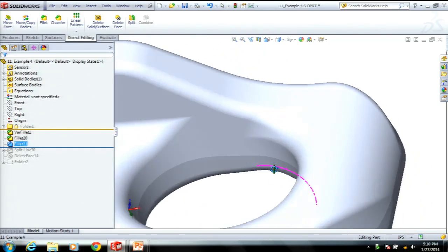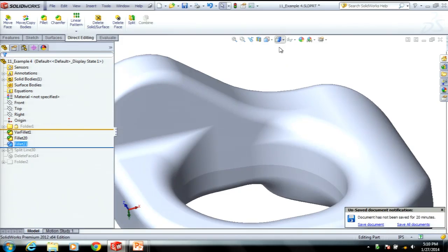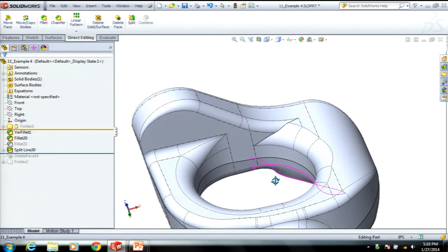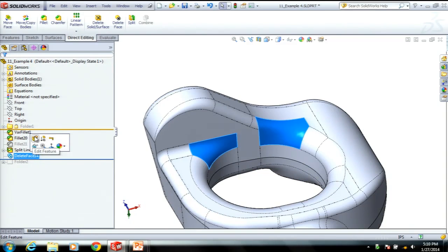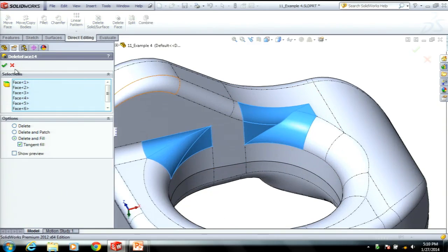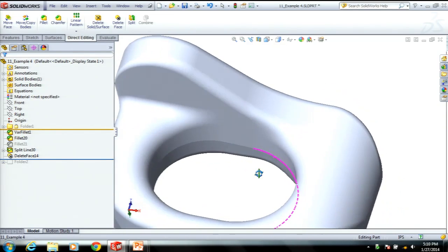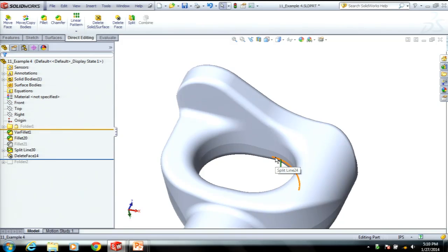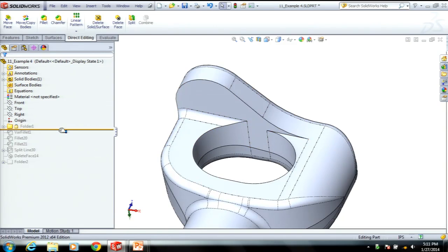It's not bad, and if I rotate the model, this could be good enough, but I can still kind of see where my second fillet was applied to the model. So I want a little cleaner transition. Once again, I used my split line tool, and you know where this is going. Delete face with the delete and fill option. This is going to take all those faces out of the model, and where I had two discontinuous sets of edges, I now have one new set of edges where the fillet of one size cleanly blends into the other. And we're in a situation where I couldn't use the variable radius fillet tool just because my starting point didn't allow the two sets of edges to be filleted.